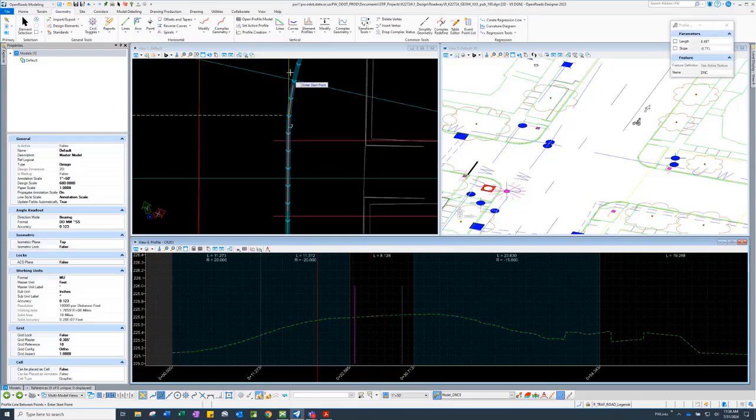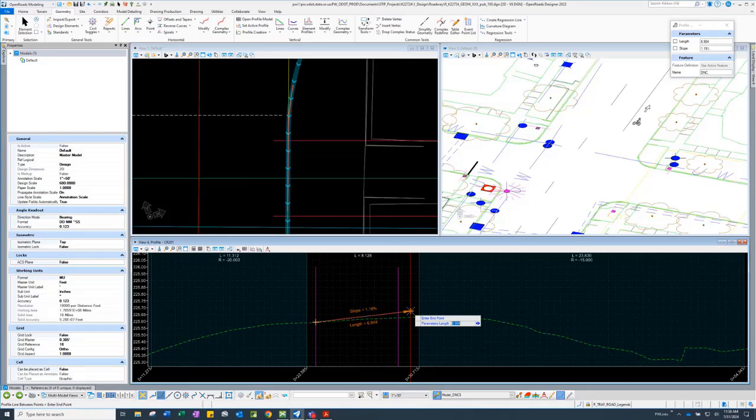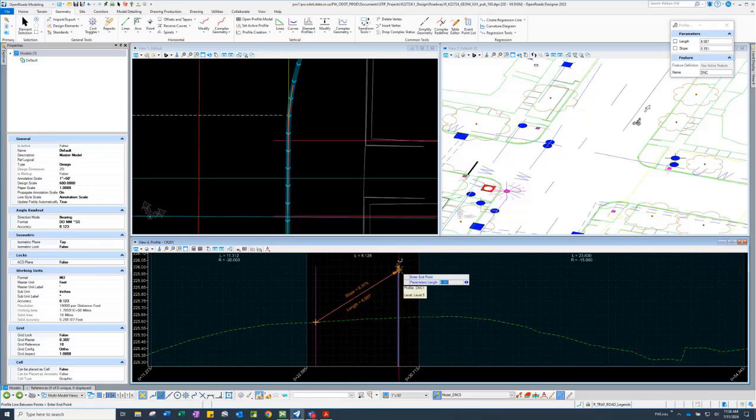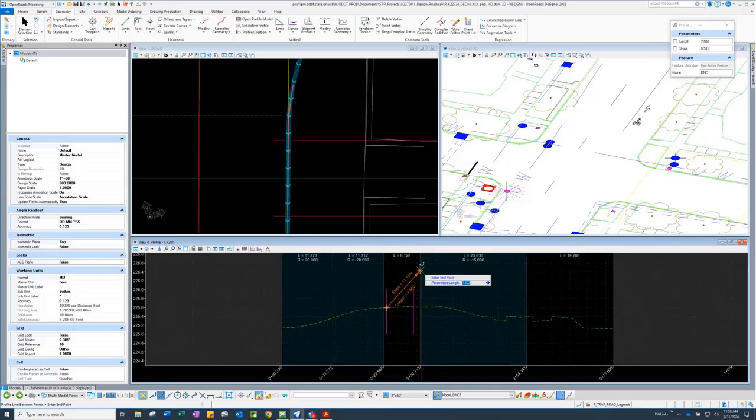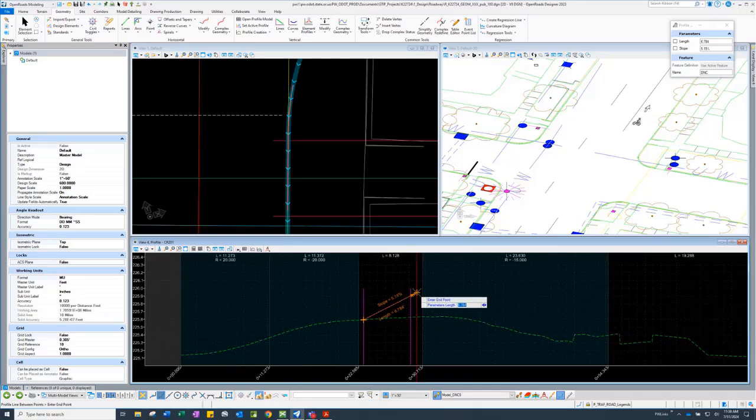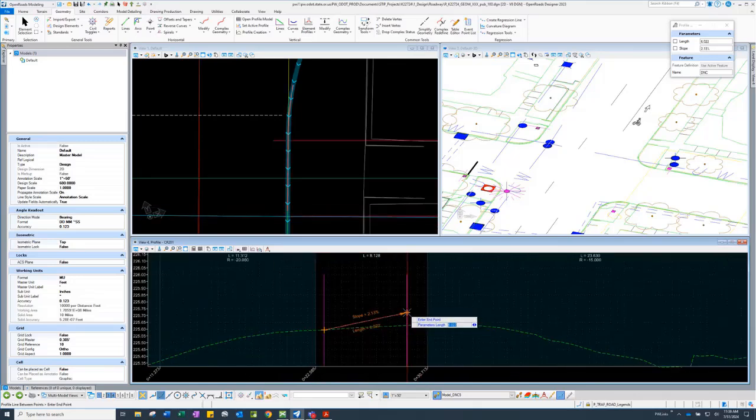I will place a 2-point line. We're going to snap it to the intersection of this point. And then I'm going to come out here. And at this point, there's a couple things you can do. You can set the length, you can set the slope, or you can actually lock it to this line. You could lock it to the cardinal point. It depends on what you're drawing. In our scenario, I just want to lock it to this here, which should be 6 feet.